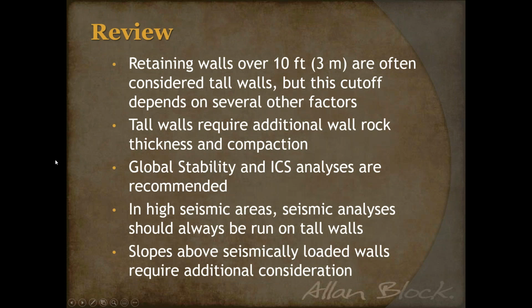Okay, so in review, we talked about tall walls, first of all, and what is considered a tall wall. Again, 10 feet is kind of that soft cutoff. Sometimes a 12-foot wall or a 13-foot wall might not have typical tall wall considerations, but a 10-foot wall with a lot of other factors involved, such as slopes and surcharges, is kind of the cutoff for a tall wall.